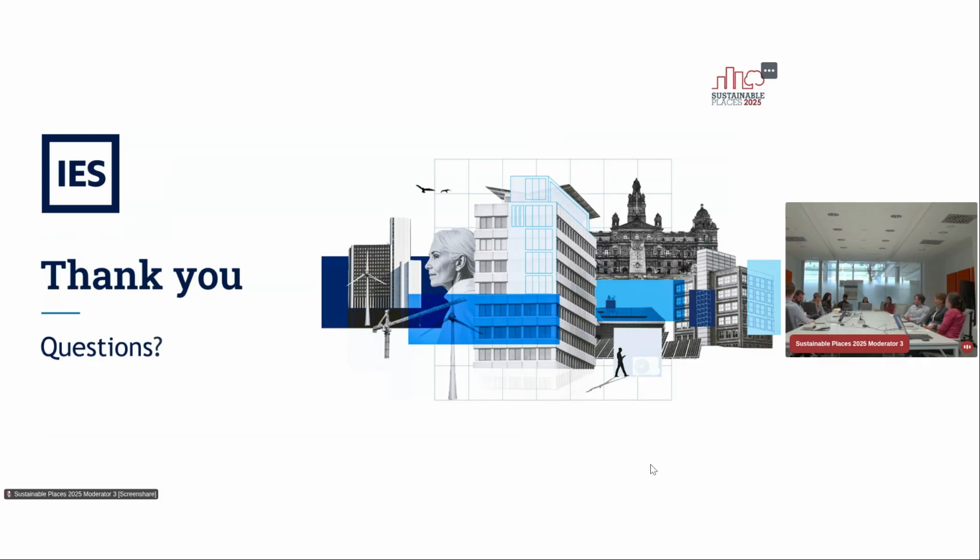Anyone else? Yeah. Just again, a question about the digital twin. A basic version of a digital twin for a building is to have the temperature sensor and understand the power consumption per section. These are the typical data needed to create a digital twin. Or now more and more in Europe, you have the power demand every 30 minutes. If you take that, you can already start to have a digital twin, because if you have heat pumps, lighting, etc., you can start to calibrate your model. So in sub-hourly data, it's already very fine.